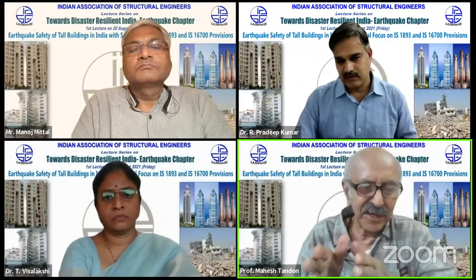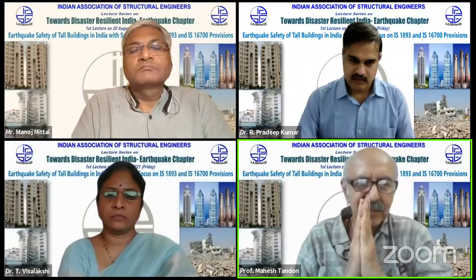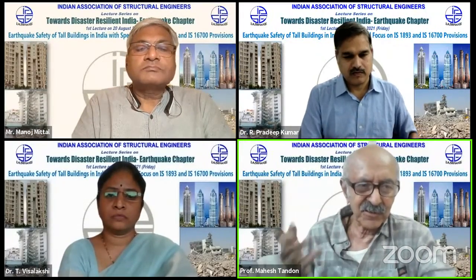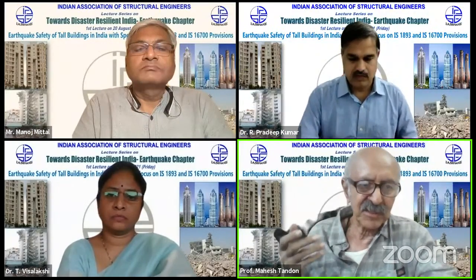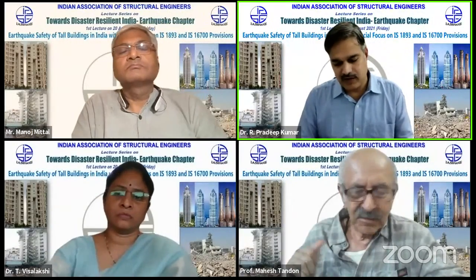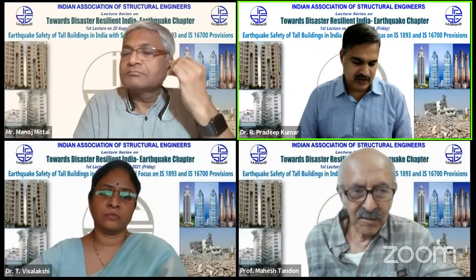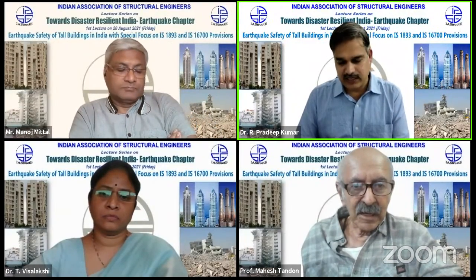You must remember that with shear wall buildings, they will automatically deflect the floors, the frames in the direction in which they are moving. So they must be designed for something, and they have said that it should be 25% in the code. Okay. And there are restrictions when we use the shear wall type of building on the response reduction factor also. Maybe I'll discuss in the next lecture. Okay, today time is not there, but on the response reduction factor also there are restrictions.